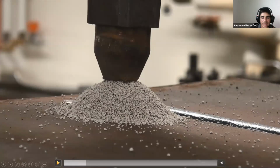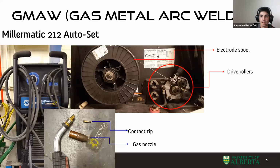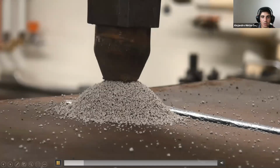One thing I like to mention here, and I would like to go back again, is that although we say that this is a submerged arc process and we shouldn't see the arc, and technically you don't need a welding helmet, it's good to be protected, or good to know that at some point the arc will be exposed. You can see how the arc is exposed in this case actually.